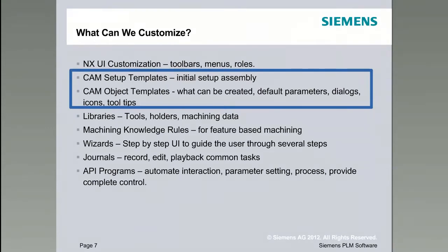Are there preloaded tools or not? Are there operations already there or not? How many geometry groups? How many MCSs do you have? All these kind of things for your starting point are part of the setup template. Now, the object template is everything you add after you start.